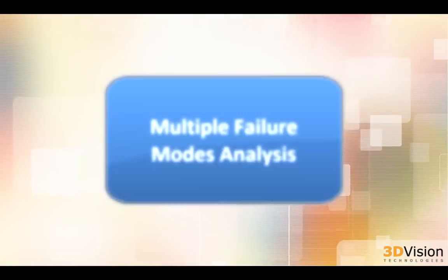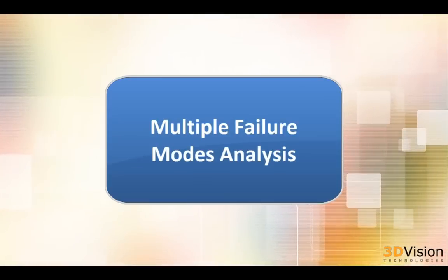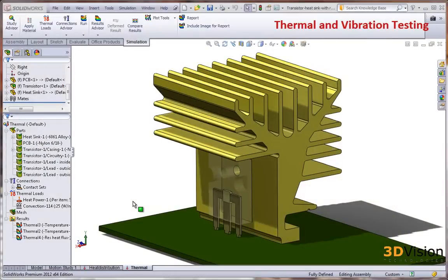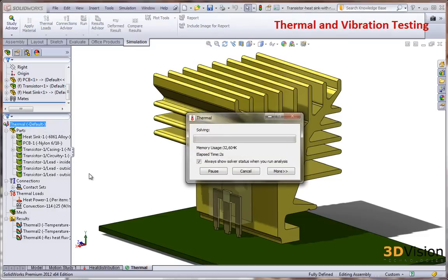Reason 3. Analysis of multiple failure modes such as thermal and vibration testing. Thermal management is an important design criterion when working with bodies generating heat. The chip shown here is generating 5 watts of heat power that is being conducted into the casing and the connector pins. A quick thermal analysis can be done where the heat source and the rate of convection are defined to account for the net heat transfer.